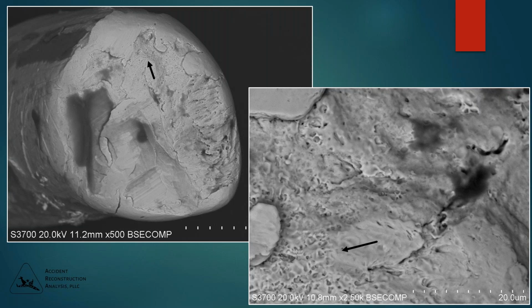It shows the magnet wire was probably partially intact, or at least close enough to make electrical continuity for some period of time before electrical arcing damaged it to the point where it failed. So again, manufacturing defect in this component.